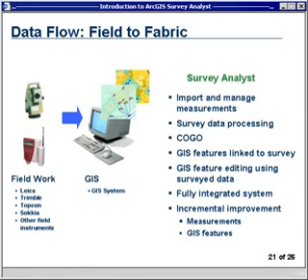So within Survey Analyst, I've loaded the data, I've computed the survey. Now I can link my GIS features to the survey points. I can also edit my GIS features using the survey data. So I can adjust those points, those GIS features. I can move them in coordinate space. I can also digitize right off the screen, off of survey points, and create new features. So as you see, this is a fully integrated system where you take the data from a collector into the GIS system, perform survey computations, and edit the GIS.